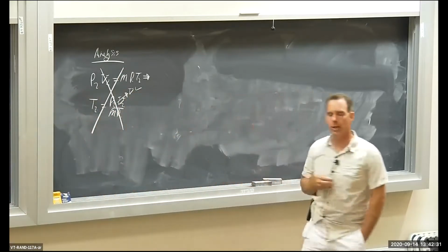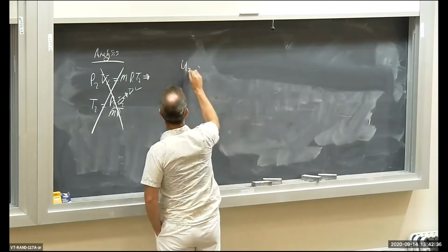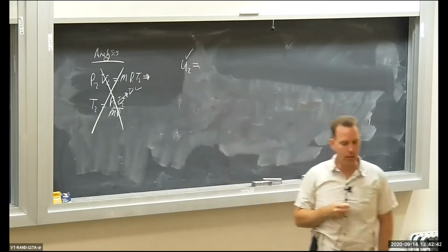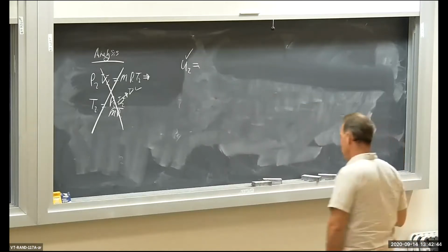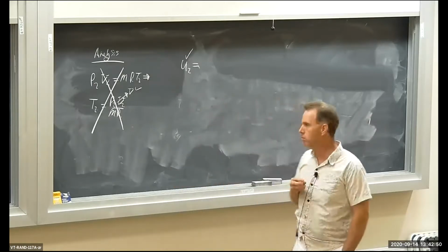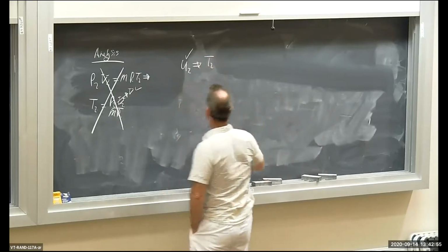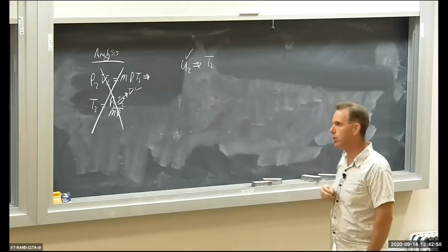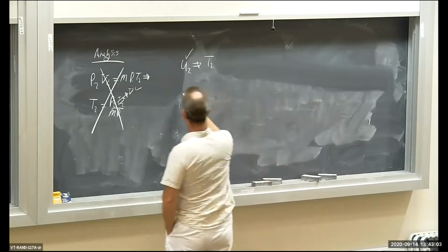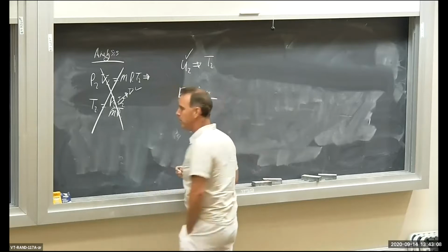What's another way we could do it? If I have the internal energy at state 2, then I could go, let's say, to an air table, and back out the temperature T2. So if I have U2, I can get, in theory, T2. So how do I get internal energy at state 2? Well, let's write the energy balance.